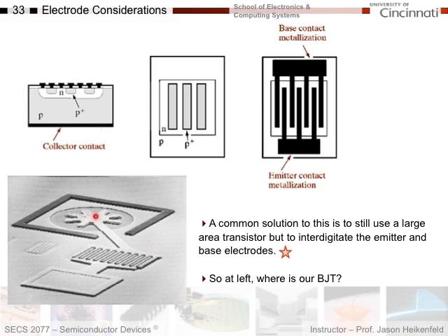What's this weird thing here? I think this is just a solder contact. If you put a ball of solder here, this shape automatically centers it in the middle, so that when you wire bond to this thing, you'll get a nice little soldering contact just like that. That's why I'm guessing this is the base, because the input to the device that you would control might be a little base contact like this, but I can't tell for certain.